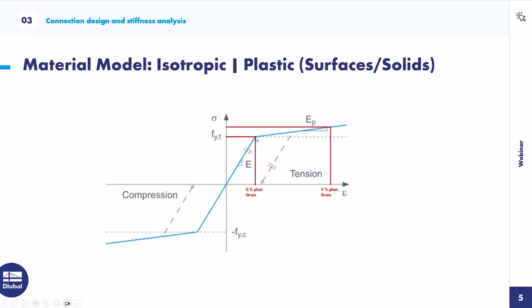That means you can't increase the load by a factor of 5 or so. That's not possible, because that's the area of the plastic strain, and we already have an elastic stress and elastic strain in the model.